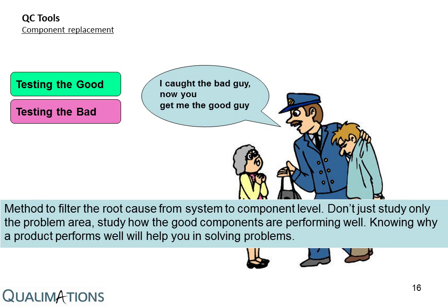Component search is part of statistical engineering, as developed by Shainin, a contrast-based approach to problem solving. Statistical engineers ask what's different rather than what's wrong. They look for the largest source of variation, not all possible causes. They avoid identifying lists of potential variables until the convergent process has substantially narrowed the possibilities.